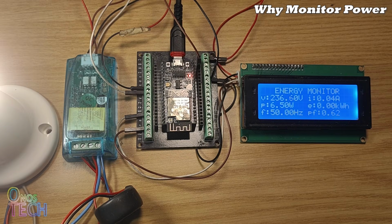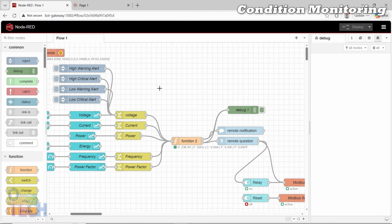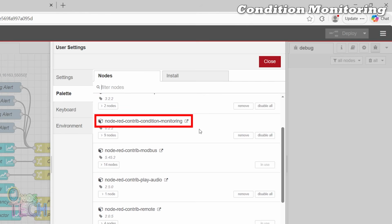Preventive maintenance application of machine learning using the PZEM-004T will allow us to detect the moment a failure begins, months before total functional failure occurs. Condition monitoring catches problems early by detecting deviations as small as 5% from the normal operating values. For this purpose, the condition monitoring nodes can be installed from the Manage Palette menu in Node-RED.